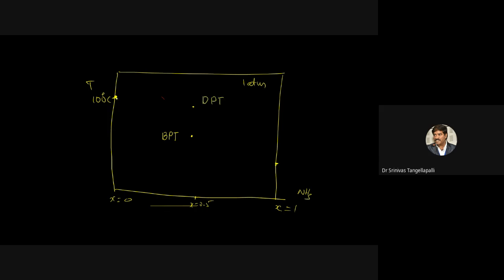But for the single fluid system, there is no bubble point temperature and dew point temperature. That is a constant temperature. What we discussed in the Rankine cycle, the evaporation takes place at constant temperature. After the economizer, we studied the evaporator and then the superheater. This is a horizontal line. But in the binary fluid system, it is not a horizontal line.